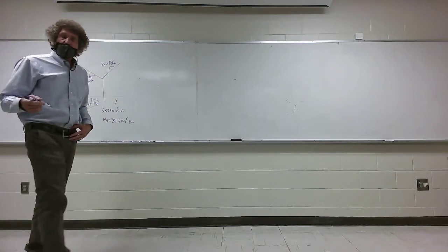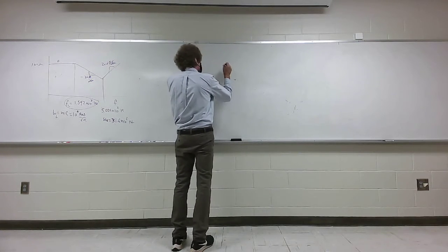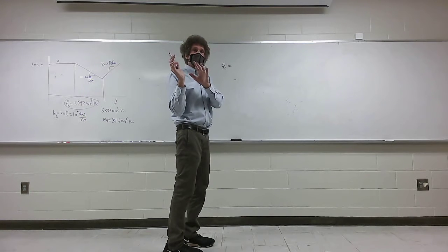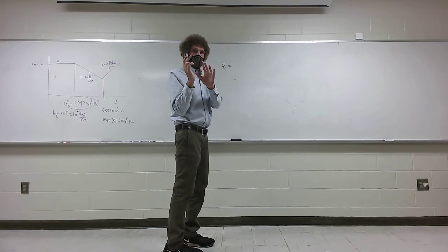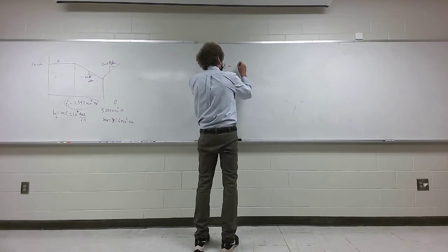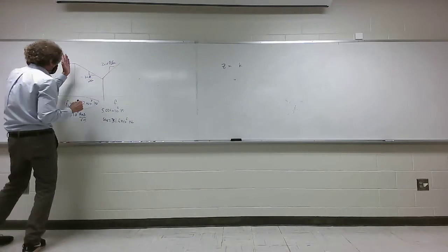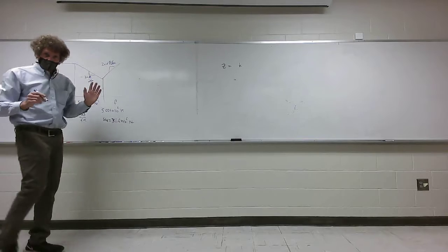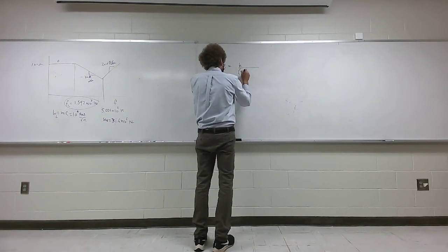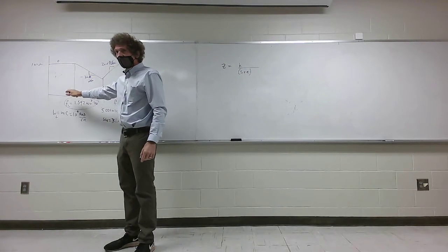All right, now, when you do this, the way you might have been taught, for this impedance Z, remember what I said, that all the constants would come out in front, right? But what I'm going to do first is just show you the general function before the constants. So it's K, and now I take a look at this. I know I have a pole down here. So I'm going to divide by S plus A. That would be this pole right here. That's the low frequency, right?